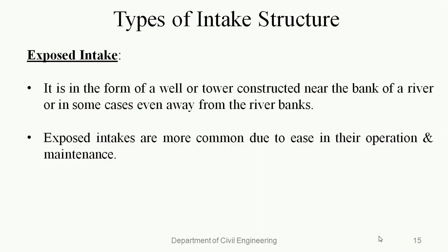An exposed intake is in the form of a well or tower which is constructed near the bank of a river, or in some cases even away from the river banks. A fair amount of the structural part of the intake is exposed above the available water level in the source. The exposed intakes are more commonly used in practice as compared to the submerged intakes due to ease in their operation and maintenance.